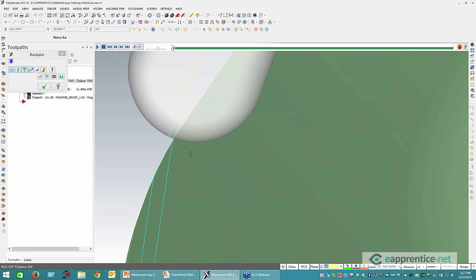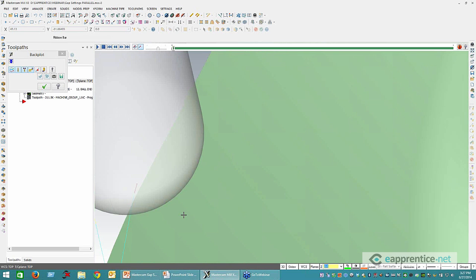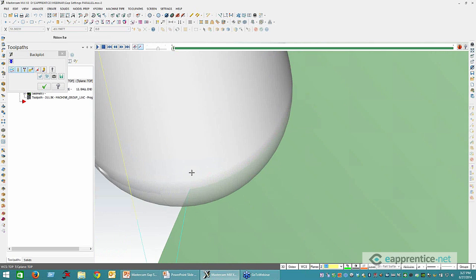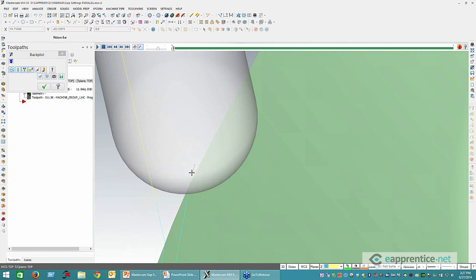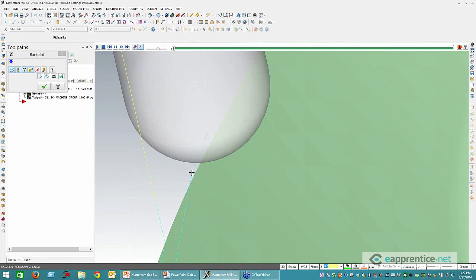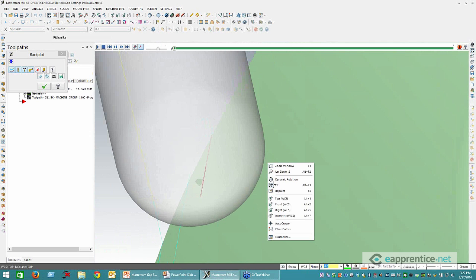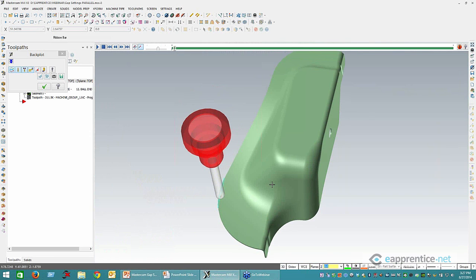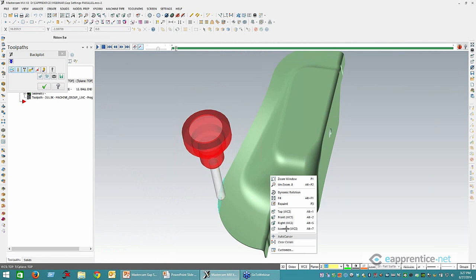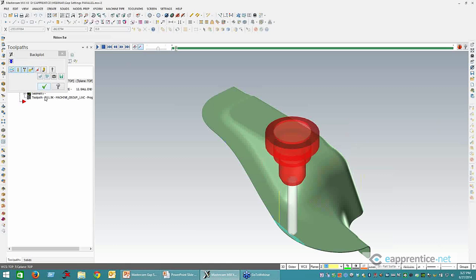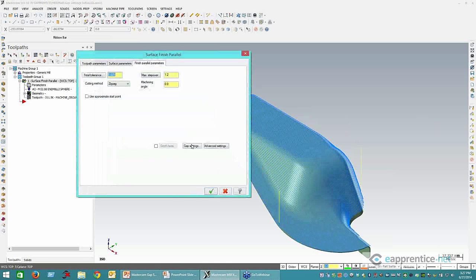What we've done with that smooth setting is cause the tool to feed off, loop back around, and then continue its cut on the part. So we loop off, come back, and we loop back on. Let's look back in isometric. And let's continue looking at our gap settings here.